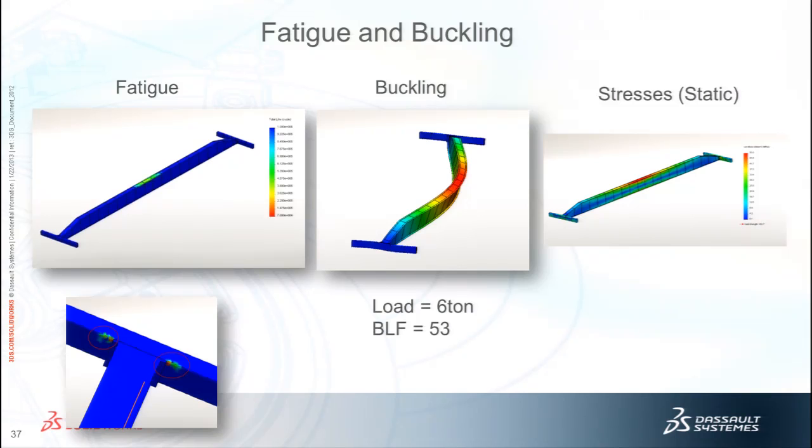In this case, fatigue was also run. Fatigue is simpler than the first case, because in this case we have a natural fatigue. It's not variable amplitude. It's the same amplitude always. So it's very easy to run in simulation. The main challenge with fatigue is to have a good characterization of the material. If you don't have a good characterization, I don't recommend running fatigue.